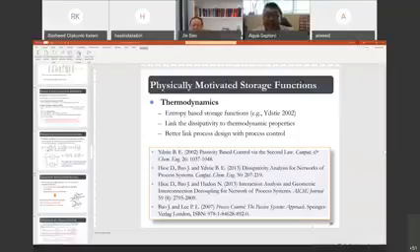Now, what I presented today, they are model based. So I'm not exactly sure about the issue you're talking about. I think the issue you're talking about, I assume that you probably don't have a model to start with, either. So you do some experiments, based on the response of the process, to get, for example, linear models using system identification and use those models in the MPC design.